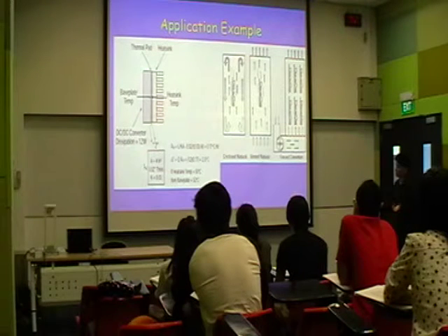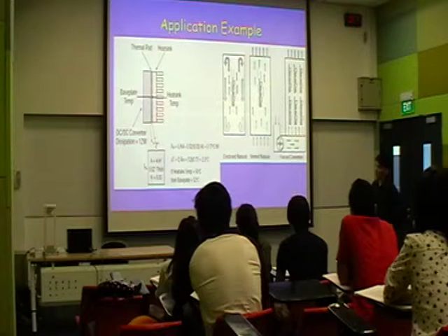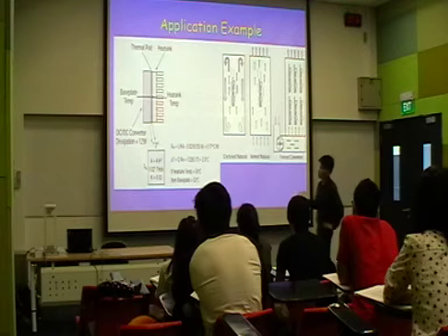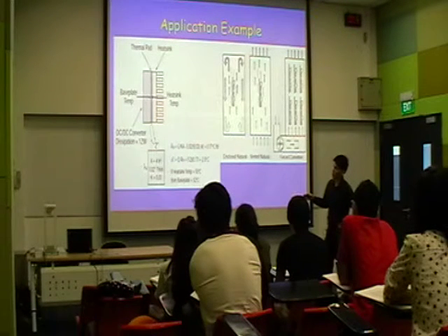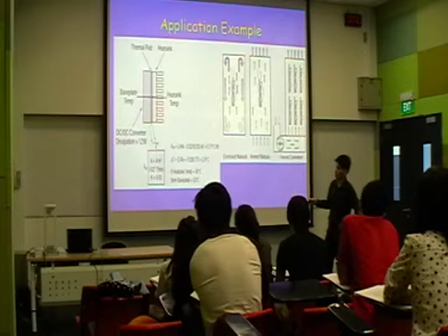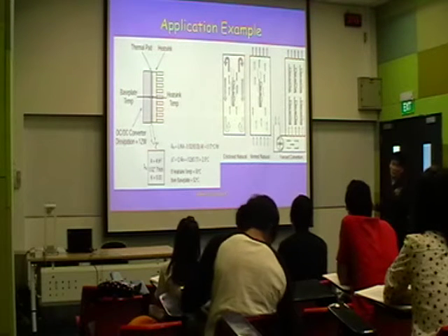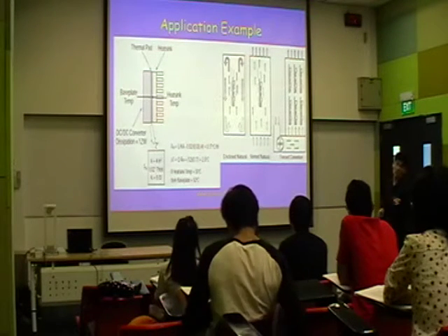For this case, the resistance is based on the thermal conductivity of the material. This one is inherent to the materials that you use, as well as depending on the surface area. All right? So you get 2 degrees. Meaning that from the base plate, let's say we start from 52 degrees, what you will experience further away from this electronics is 50 degrees. There's only 2 degrees of temperature loss. The higher the better, but this one can only offer a 2 degree change.